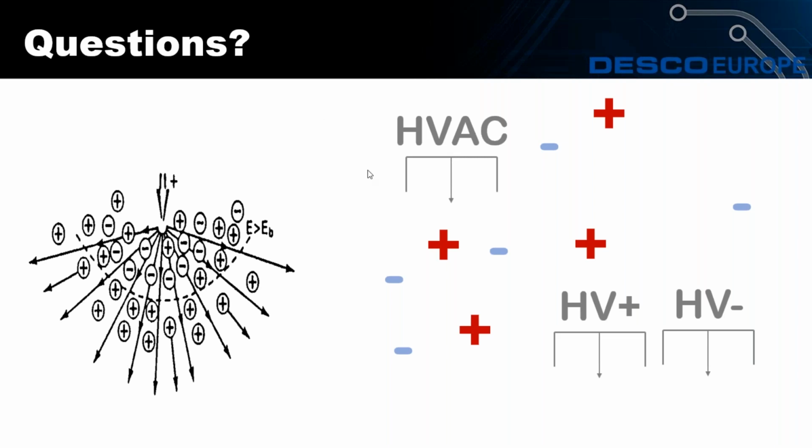Yeah, the European standard we will cover. We'll go into that a little bit more later on and show you the excerpt from the standard. But their recommendation is that the offset voltage, so an excess of either positive or negative, must be less than 35 volts. And as Stephen said, it's the same terminology. It's different terminology, but the same thing. Balance and offset voltage. It really means exactly as we've just described.